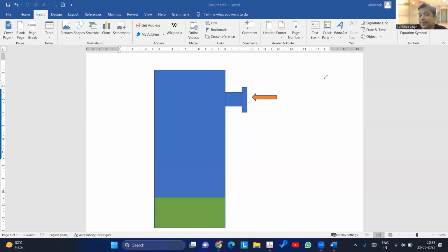Now let us open PV Lite and see what option is there. And then it will complete. So still we are talking about only the first part. I'll come back with the second part, which is derating, and also the third part, which is saddle support, and what will be the effect here at the anchorage or the skirt. The fourth part, which Uday also missed, is the nozzle neck. There will be additional stresses coming at the nozzle neck also. That also needs to qualify. That is the fourth. So 4 calculations, only because of this nozzle loading.